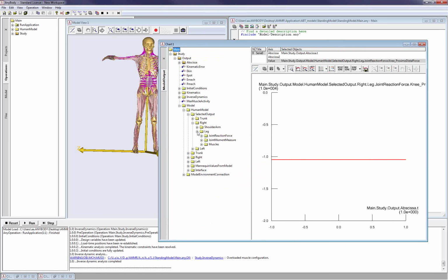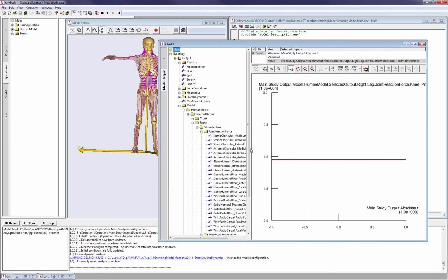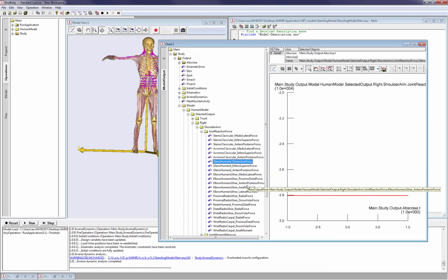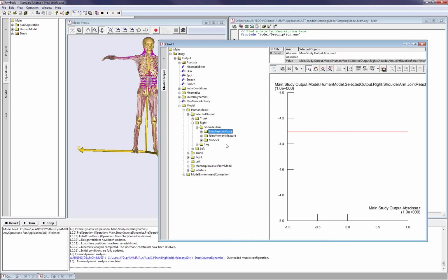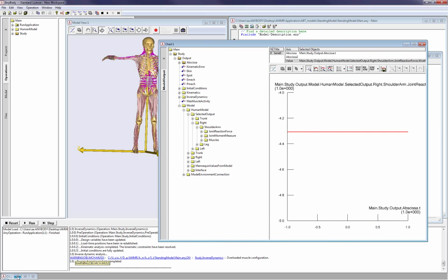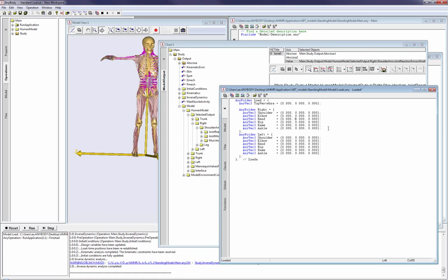We can look again at the arm, for example. So if you look at the reaction forces in the glenohumeral joint, would be here. So we have 1700 newtons in the shoulder and the anterior posterior, and even more in the distraction force. So clearly that was too much, so we're going to change the force again. So we'll remove the force in here. So in here you can of course apply different load scenarios.